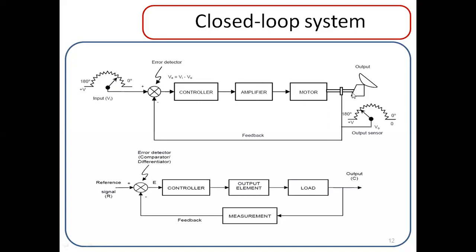So if the rpm, rotations per minute, has decreased, simultaneously the voltage levels will be varied. So incrementing the electrical emf or voltage levels at the input level lets the controller and amplifier rectify or reschedule the control parameters, and provide the higher voltage to the motor to increase the speed. So whether that speed has increased or not will be verified with respect to the inspecting device.